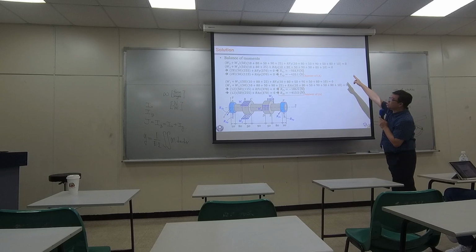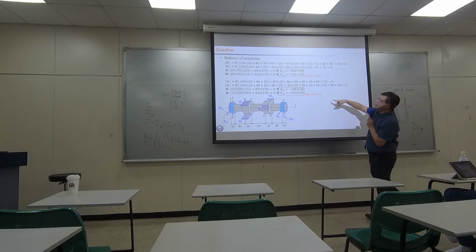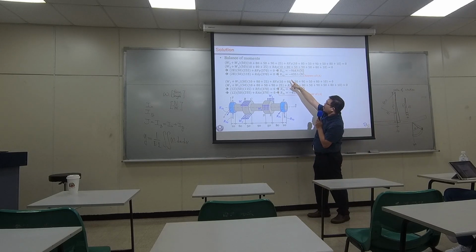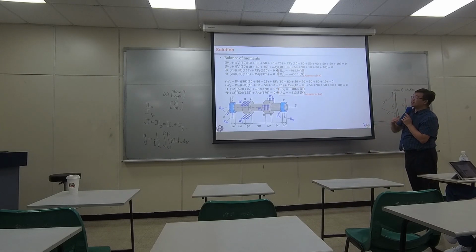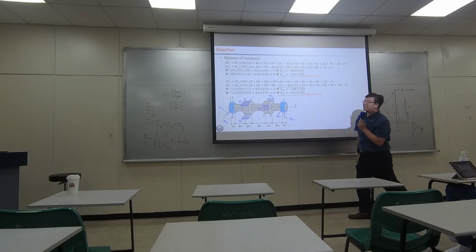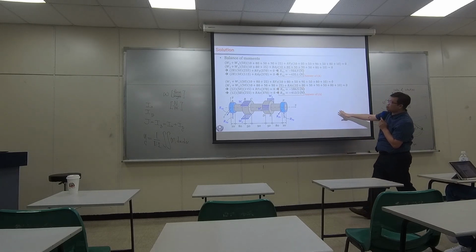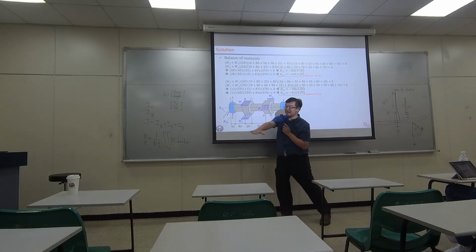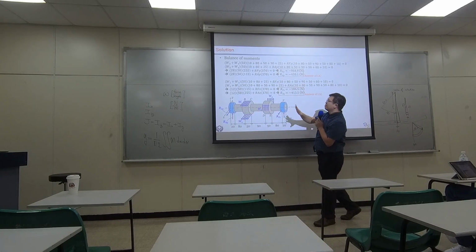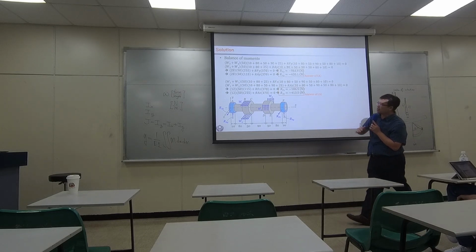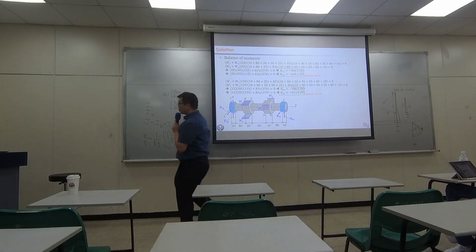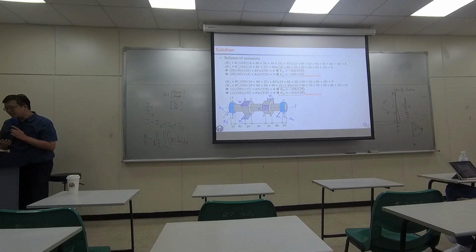So with those two equations, do some math, you can get RFY and RAY. Okay? And at the end, if you get negative values, that's fine. That means they're actually going down. Similarly, I'm working on the XZ plane, the horizontal one. Very similar procedure. I don't want to spend too much time, so check it on your own. Now, that's everything I need for the answer A.